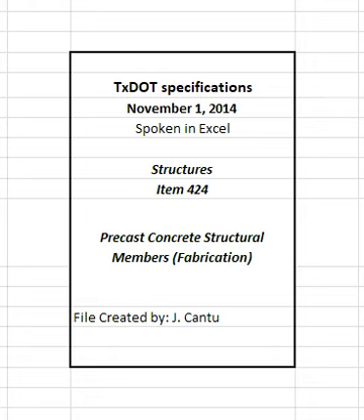4.3.2.2 Non-stressed members. The allowable tolerances for non-stressed members are as specified in Table 4 unless otherwise shown on the plans. The allowable tolerances for non-stressed wall panels, except MSE wall panels, are as specified in Table 3. Table 4. Allowable tolerances for non-stressed members. See table in specifications. 1. Includes wall components for tieback walls, sea walls, sound walls, etc.